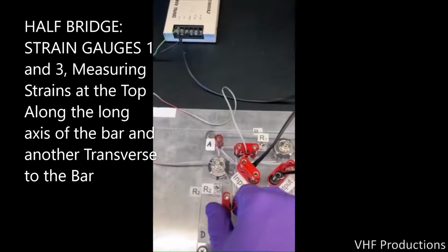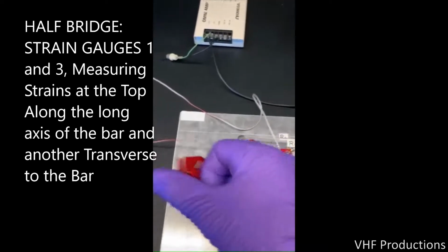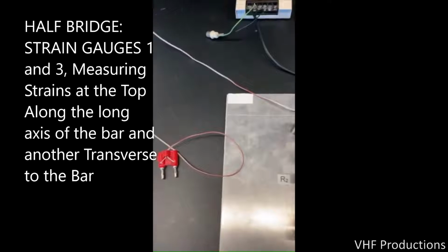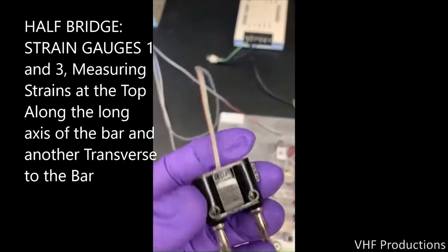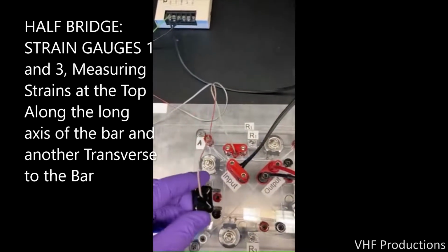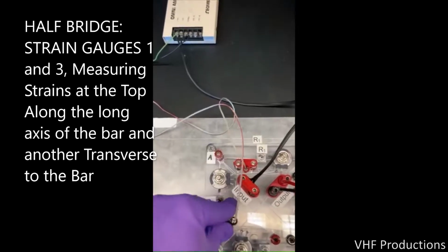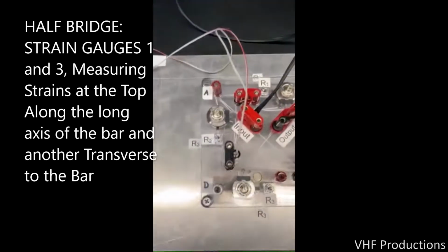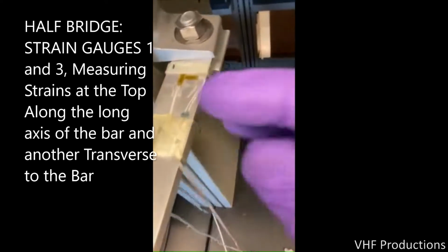In the third configuration of the Wheatstone Bridge, we're going to use the top surface longitudinal gauge, the first gauge we used, and we're going to combine it now with the transverse gauge. It's the same strain gauge as the first one, but it's now rotated 90 degrees relative to the surface of the bar. It's also located on the top surface, back at the hinge point.